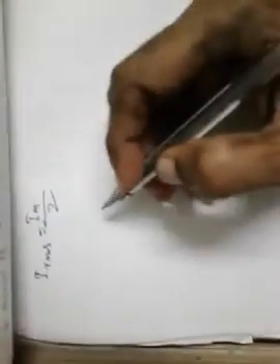This was the expression. You can once again recapitulate to find this formula over there, where RMS value of load current, IRMS, also we have found over there, and that IRMS is nothing but Im by 2, as we have found in the derivation previously. So Im we have already found 0.353 divided by 2, and so this is 0.176 ampere. So now we have in our hand IRMS and IDC. Substitute the values to find.